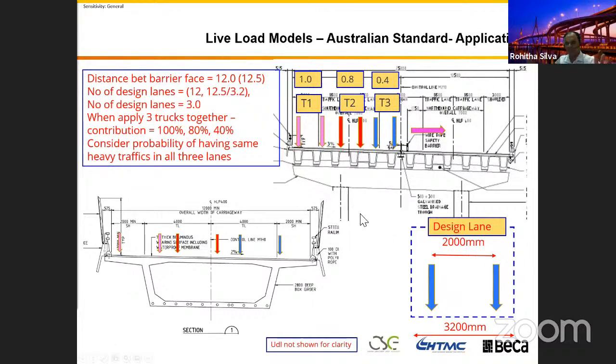Then, yeah, you can design your bridge, because you can develop thousands of load cases, but you know exactly which load case is going to govern this bridge design. That is what at the beginning I said, look at dead load and look at live load on your bridge. You design for that and check for the rest, right? If you understand up to now in this one, I think you know how to design a bridge.